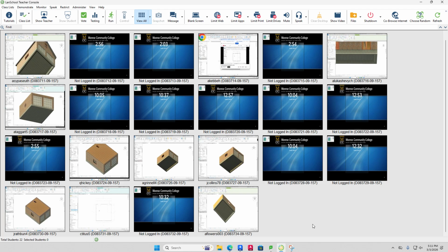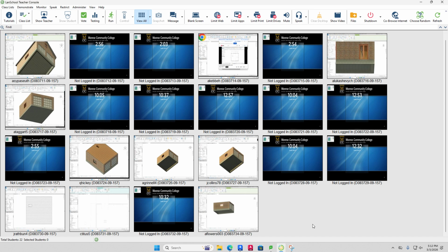It's under the structure tab, and it's called a slab edge. You click the edges of the floor you put in. So am I using the line or am I using a square? You want to use the rectangle. You could use either, but the rectangle's easier. And you want to go outside edge to outside edge. Yep.